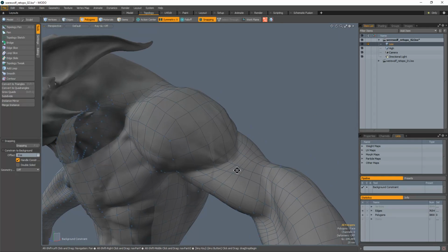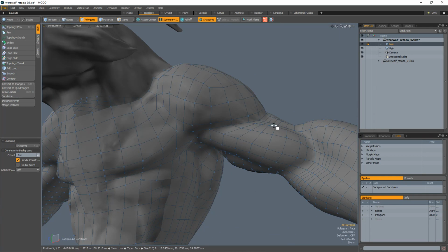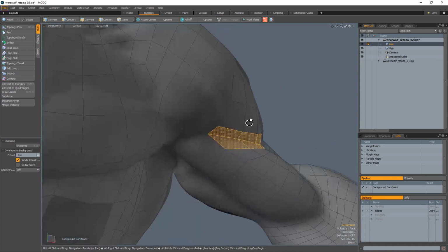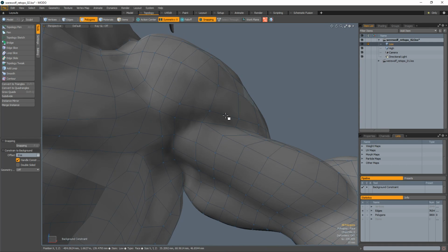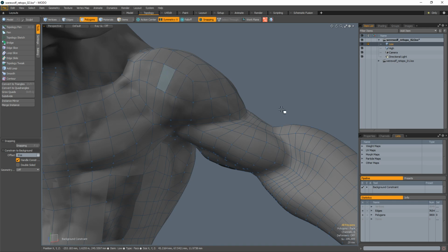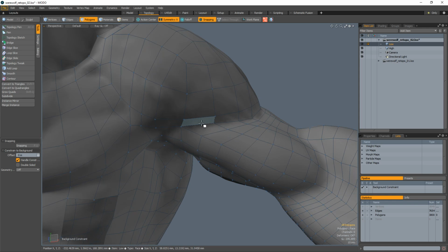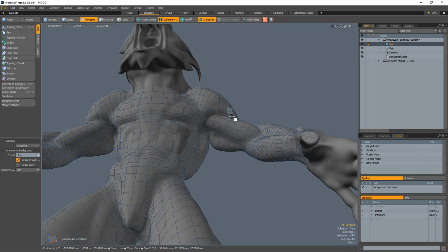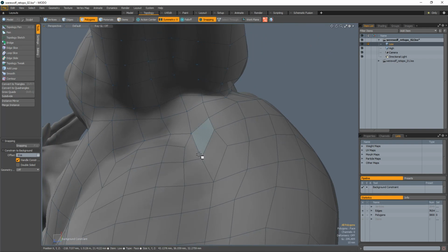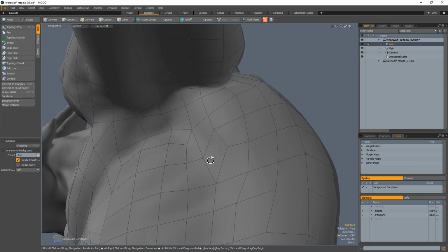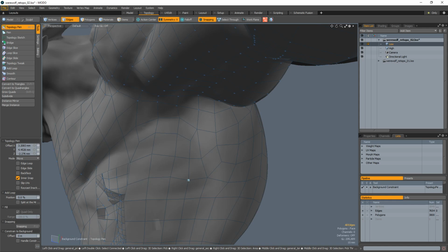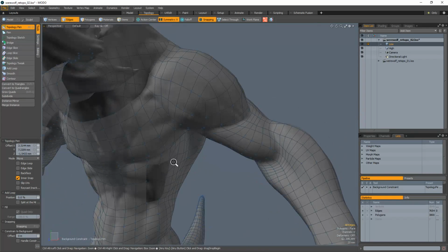Like I mentioned during the last session, areas like this provide some challenges for modeling, because while you might want to make the whole thing just a simple tube, having stuff that follows the actual contours gives you much better results when it comes time to bake or do texturing, that type of thing. So it's better to not have things that stretch across large gaps. It's better to try to get the topology to conform to the shape as close as possible, as long as it's not going to provide problems for deformation.